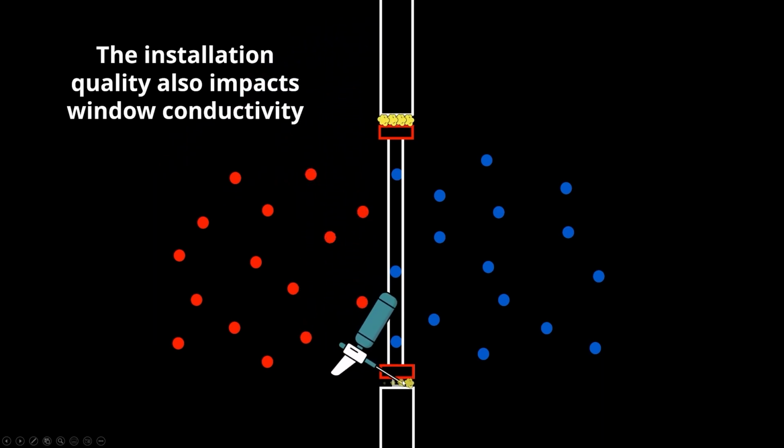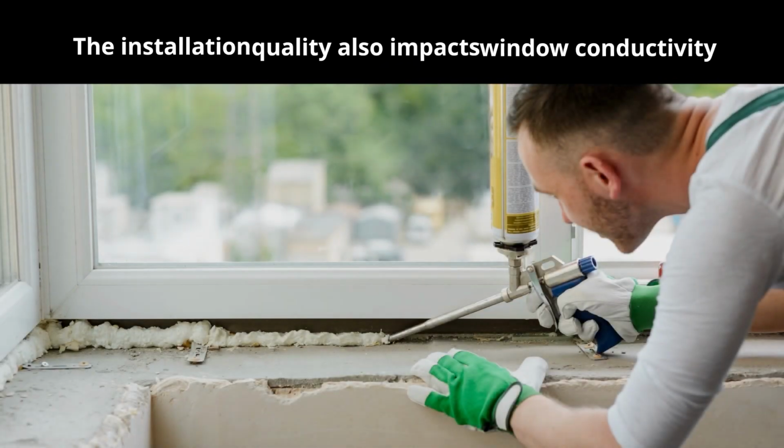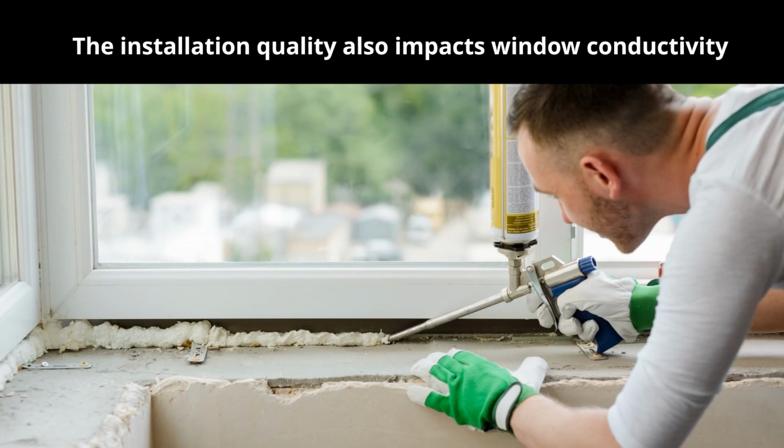There are no gaps, there are no cracks. The more thorough the work is done to foam that window, the fewer gaps you're going to have. So in this case, it looks like, oh, he's doing great, he's foaming the window. But if this foam doesn't expand all the way to the top, that's an opportunity for conductive heat transfer. So you want to make sure there's a thorough job done with foaming around existing or retrofit window frames.